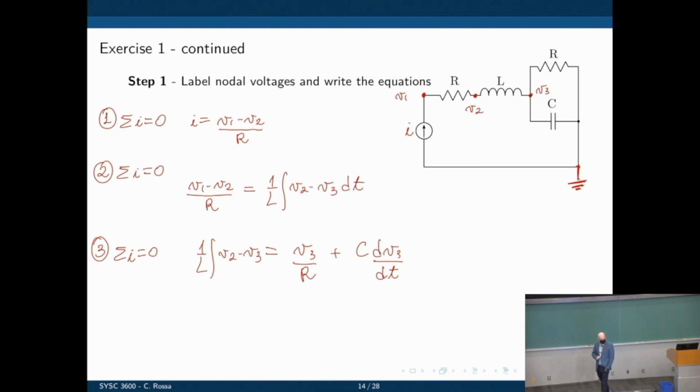They're all equivalent. Okay. So we got 3 equations. We had 3 different voltages using the nodal equation. This means that in our equivalent mechanical system, we shall see 3 different points where the position can change independently. 3 different degrees of freedom in the system. Right?